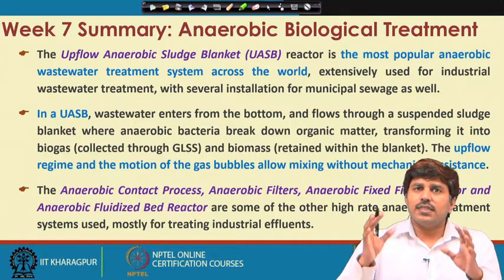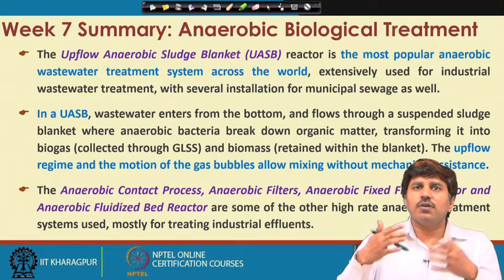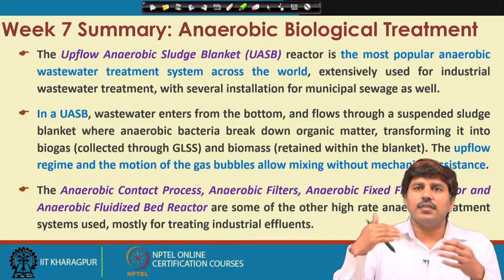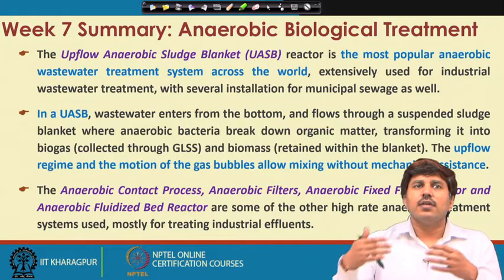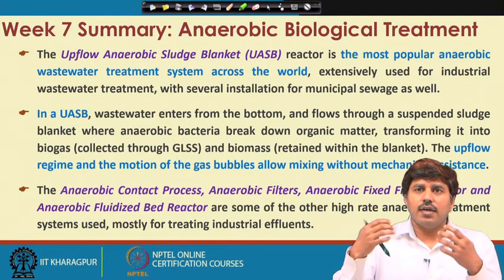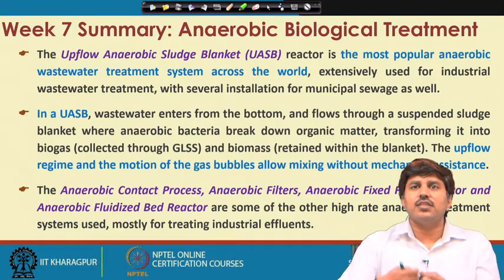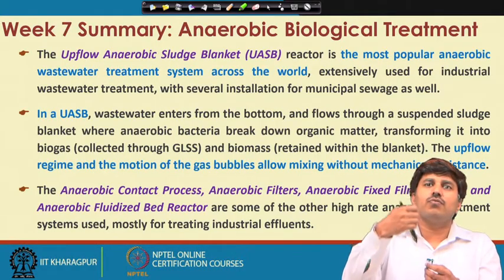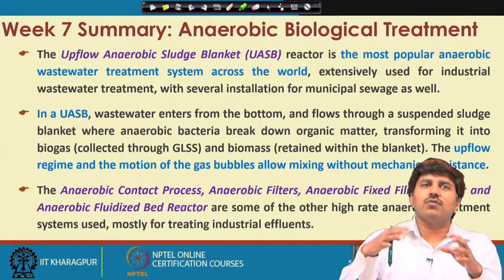The anaerobic bacteria that remain in this sludge blanket are responsible for breaking down the organic matter, and in the process they transform it into biogas. This biogas is produced in the sludge bed, but since gas has a tendency to move up, it moves up, and after the sludge blanket we have a settling zone.